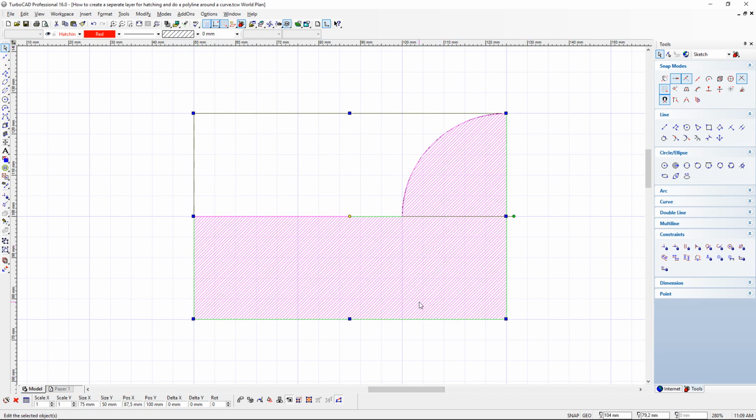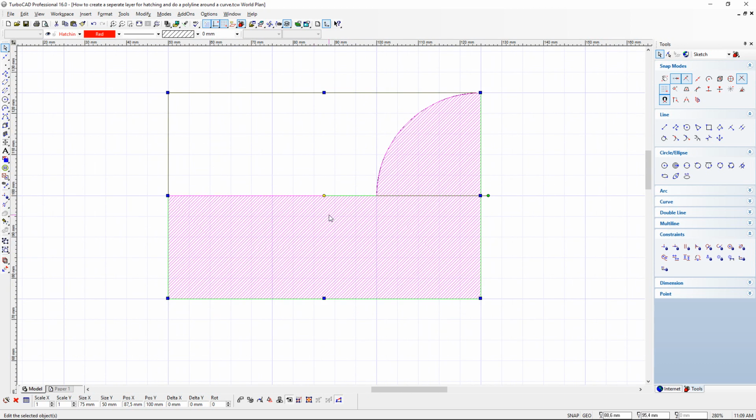But now obviously if you're a good draftsman, you will know this is way too intense for hatching. Yes, it is 45 degrees, but it's way too intense. We want to always remember the rule for hatching is that the distance between hatched lines is spread out equally in relation to the surface area of the model that you are cutting and then have to hatch.